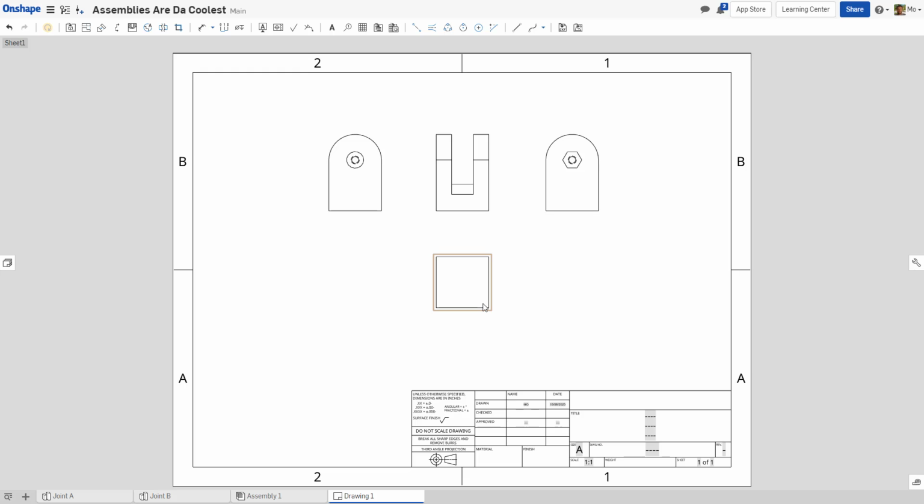One of the key rules of dimensioned drawings is to present and label everything that's necessary and nothing more. Effectively, we are trying to accomplish the same thing as we do when we are creating a fully defined sketch. We want to show all of our features, and we need to label all of the dimensions needed to create this part from scratch. However, we want to avoid duplicating any dimensions. We also need to label these dimensions and these parts clearly. To do so, it might be useful to enlarge these parts.